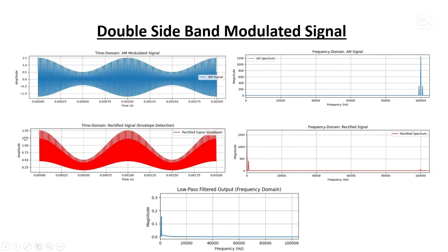All right, and if we pass this rectified signal through a capacitor, not literally passing through a capacitor, but a capacitor can be used here to eliminate the ripples. A capacitor can be used to minimize the fluctuation.